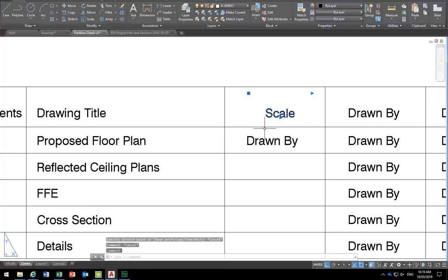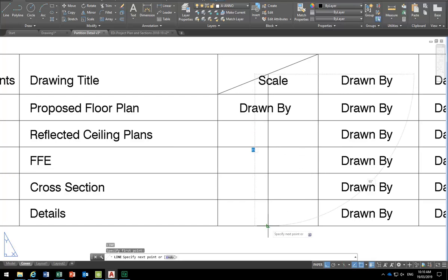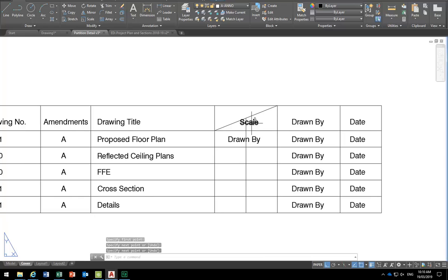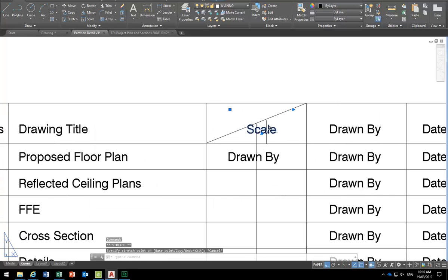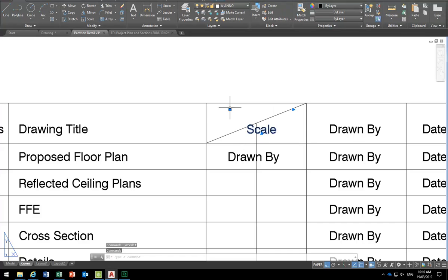So, a nice thing there, to line those up, if you draw something like a centre line like this, you can then make the text box the same size and then... Oh yes, you can, that's what I'm doing. So, yeah, that's fine. If you drag it over, if it is centre justified, you can, absolutely. So if we drag that across with the grip, so it's stretching to either side, it will be centered exactly.